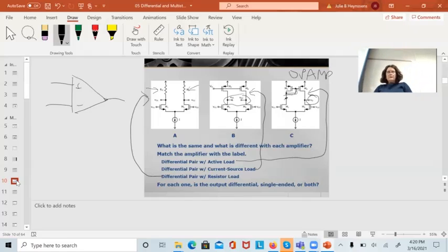Next thing I'm going to do is put a high gain CS stage on it, then maybe a buffering common drain stage on the output, and put some stuff in there to stabilize it for temperature, maybe make the input impedance super high, put a JFET input on it, build little tricks into these things to make them better for different applications. But that's basically how every op amp starts out, is that circuit right there.